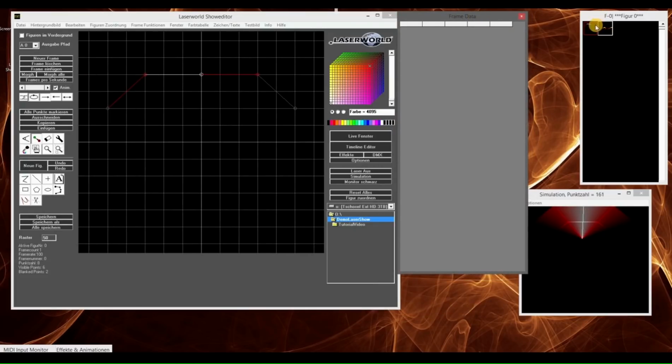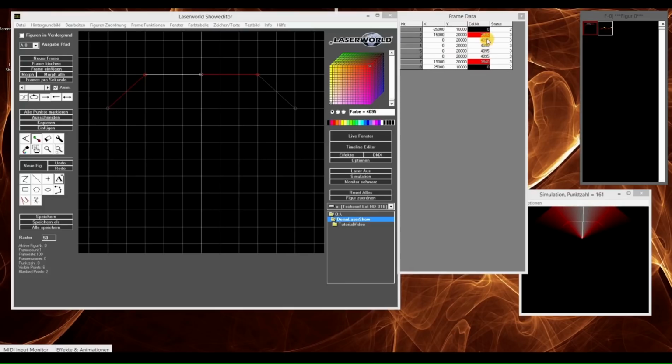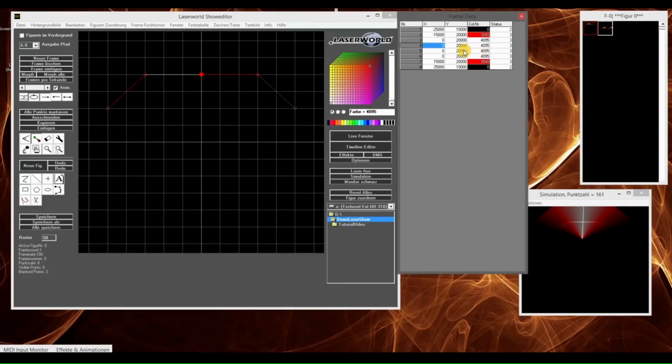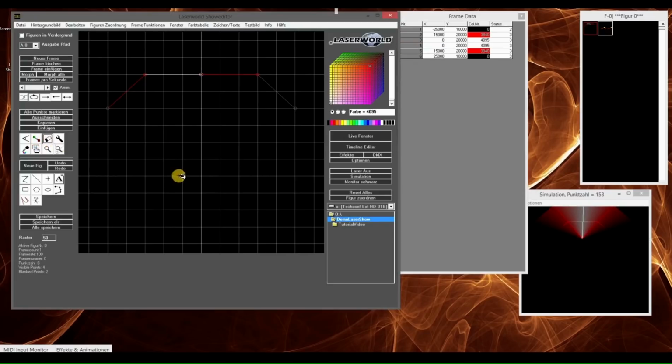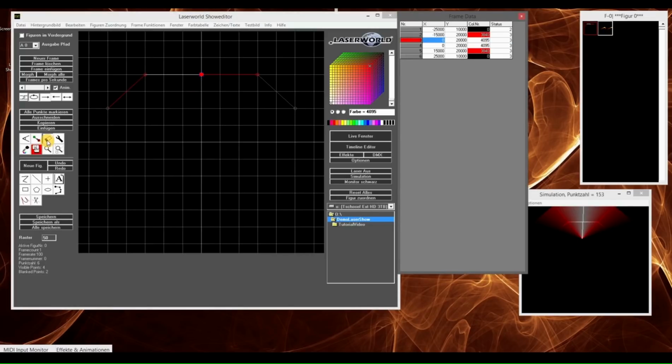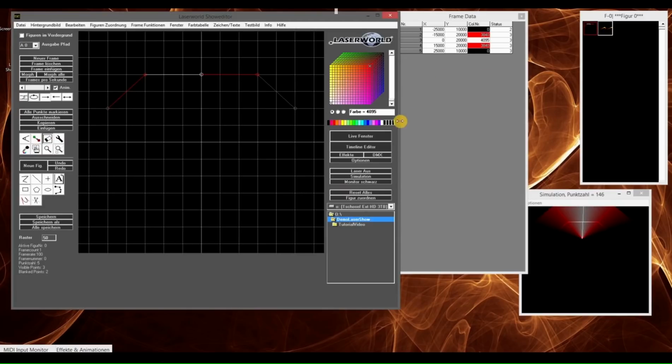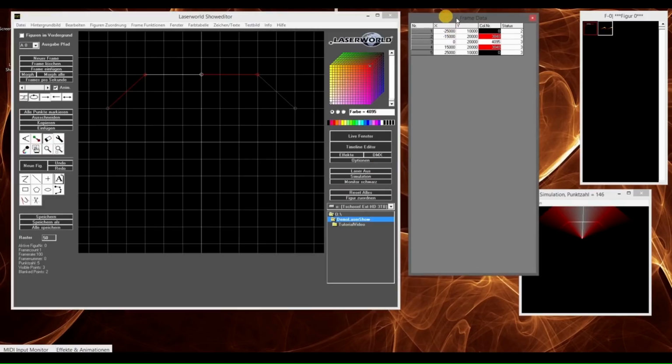This is super helpful if it comes to drawing own figures, own frames, because you can see the position and also the order of the points that are drawn, and you can also reorder the points and also delete and change settings, which is extremely helpful to streamline your drawing, to make reductions to the number of points, and also to have control over how the scanner actually draws the figure, which significantly can improve the quality of the output.